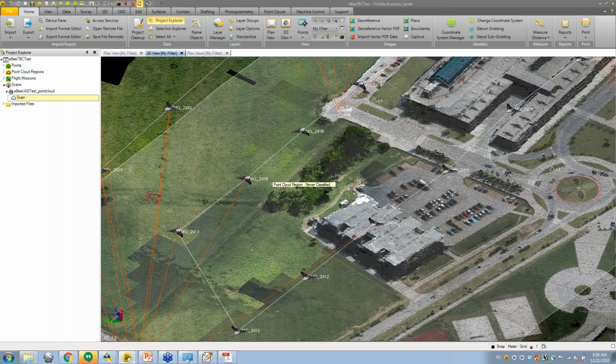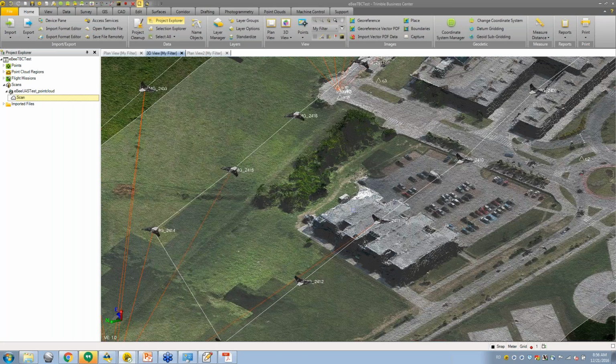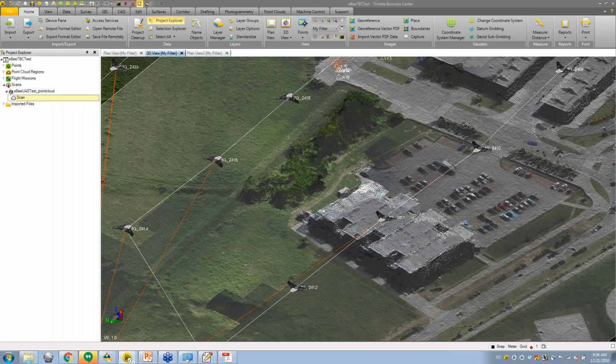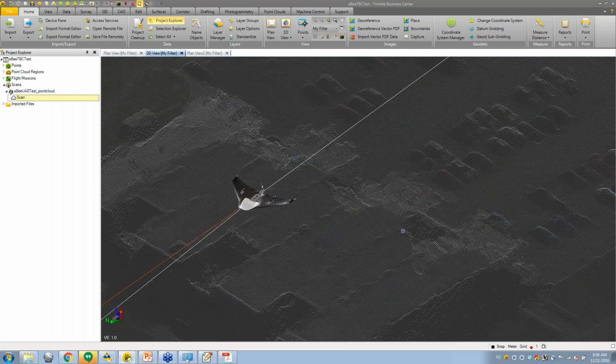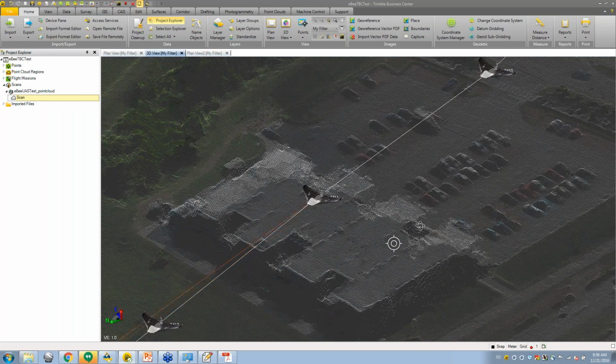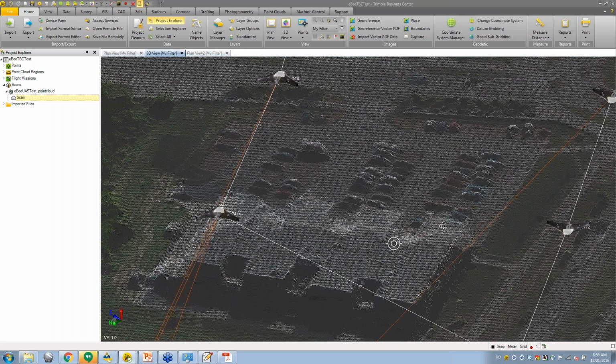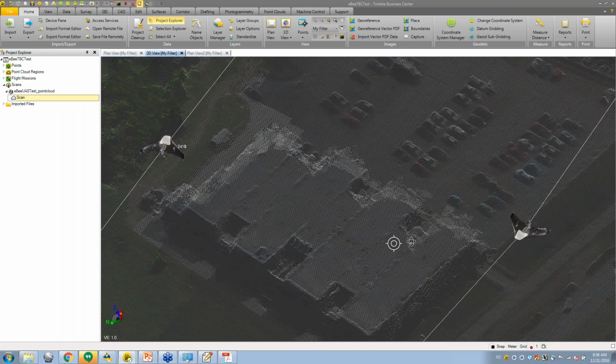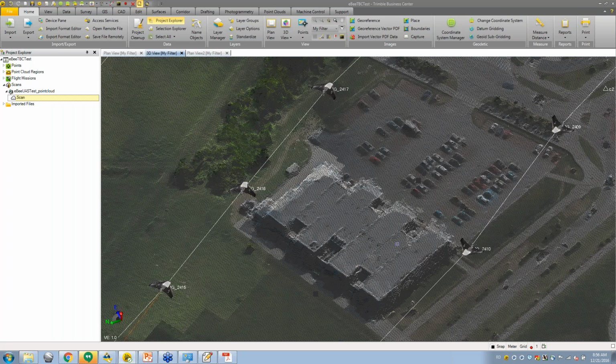All right, and it will pop up, but it will actually prompt me to accept the data I've been sent back. As everything has seemed to take a little bit of time here, it'll actually prompt me to do that in a second as well. But looking at this point cloud, you can see that it actually does a pretty good job with buildings already. There are some areas that we'd want to adjust for, but it's a pretty accurate point cloud and orthophoto that we would create without even editing. Obviously, editing is still necessary and something we'd want to do if you really wanted to model that building. But just looking at it as a land cover, it would certainly be good enough for that. Perfect. So that actually completes the workflow.